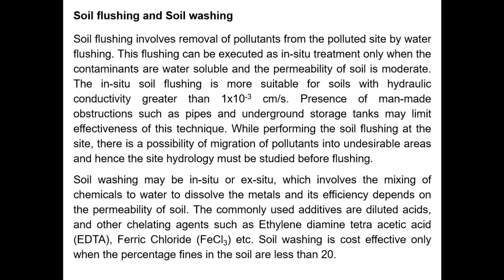Soil washing may be in situ or ex situ, which involves the mixing of chemicals to water to dissolve the metals, and its efficiency depends on the permeability of soil. The commonly used additives are diluted acids and other chelating agents such as ethylenediaminetetraacetic acid, ferric chloride, etc. Soil washing is cost effective only when the percentage fines in the soil are less than 20%.